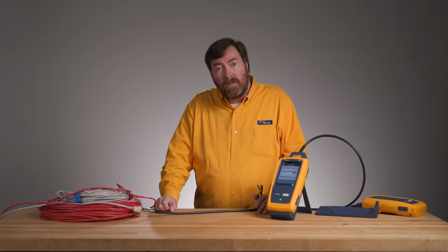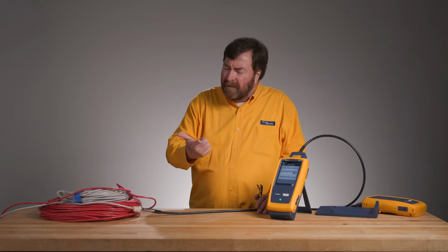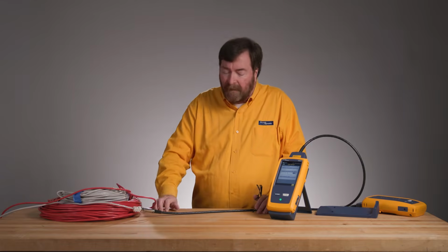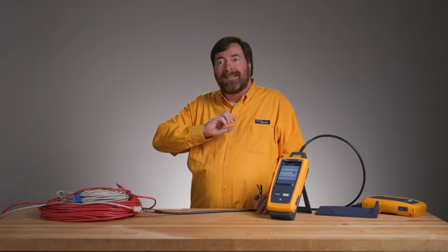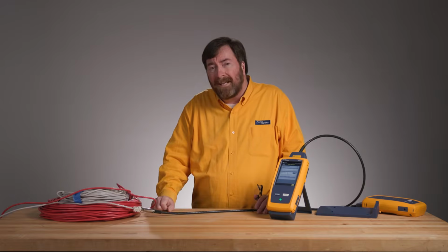Well, you might consider using powered fiber. Fiber goes a longer distance. You can use an oversized conductor to supply either PoE or the fancy new Class 4 digital fault-tolerant power, or digital electricity, to run power out to those longer distances. And you'd still be standards compliant and NEC compliant. Another way to go would be to use a proprietary extender device, something that puts out more power, something that is not PoE standards compliant. That might work great for today, but again, we've got that problem with tomorrow.